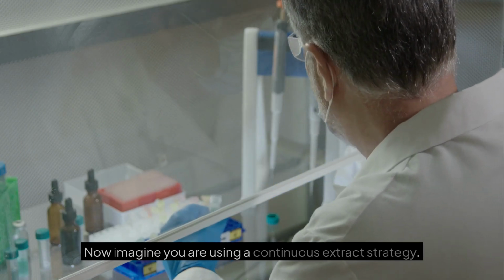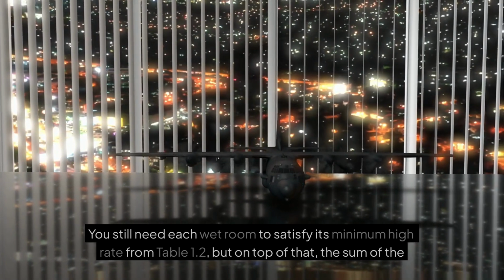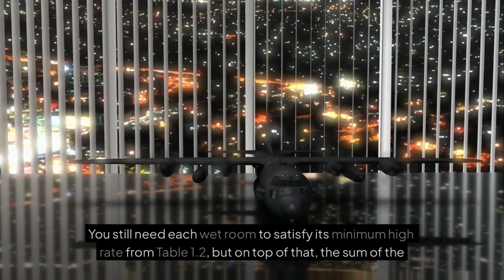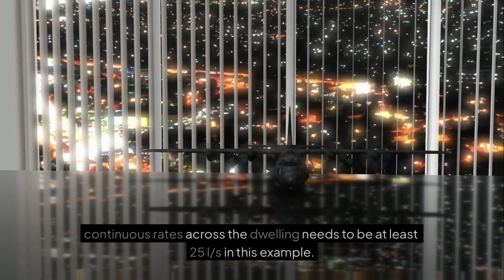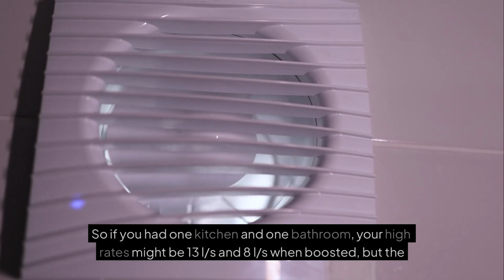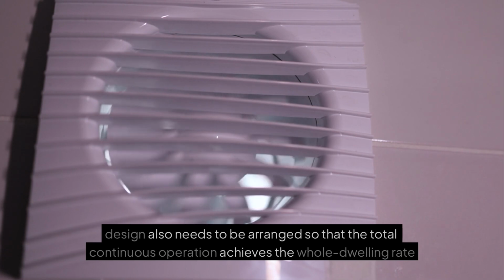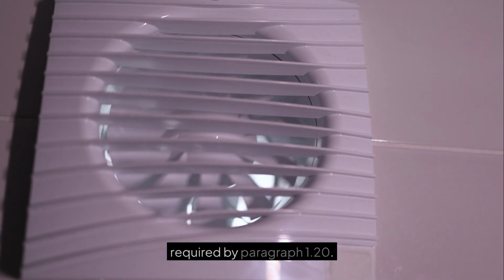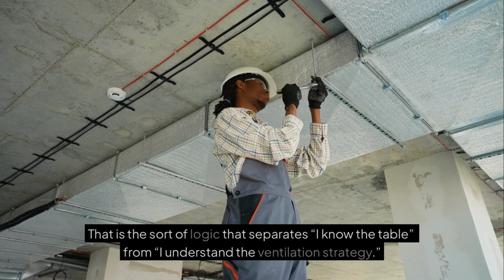Now imagine you are using a continuous extract strategy. You still need each wet room to satisfy its minimum high rate from Table 1.2. But on top of that, the sum of the continuous rates across the dwelling needs to be at least 25 liters per second in this example. So if you had one kitchen and one bathroom, your high rates might be 13 liters per second and 8 liters per second when boosted. But the design also needs to be arranged so that the total continuous operation achieves the whole dwelling rate required by paragraph 1.20. That is the sort of logic that separates "I know the table" from "I understand the ventilation strategy."